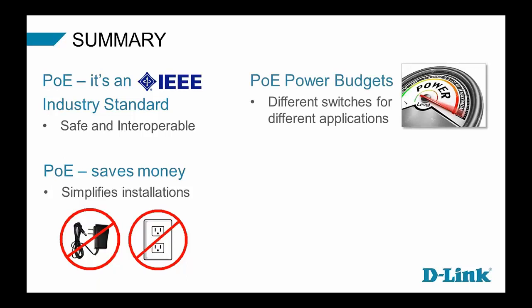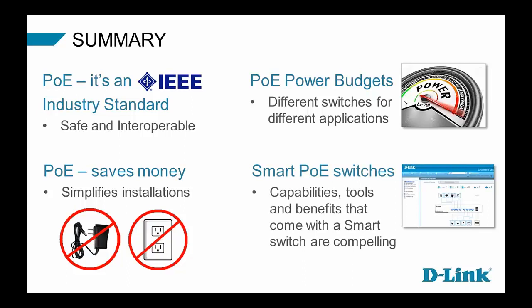We talked about PoE power budgets and the different kinds of PoE switches that are available. Some have pretty robust budgets. Some have lighter, thinner budgets. They're different switches for different applications. And it's important when you're designing a network to understand what kind of power requirements you're going to have so you can size your power budget accordingly.